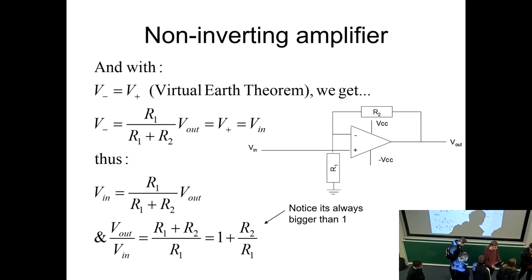So that's linked to A, that's the amplification decreasing. Yes. That's why there's a little capacitor inside the op amp. If you go back to the original side, that actually short circuits the gain stage at high frequencies. Because at high frequencies, the signal goes through that capacitor, goes around the gain stage, so the gain drops off. And it's deliberately done to maintain stability at high frequencies. Otherwise, it's all over the place. That's what we did in T9.